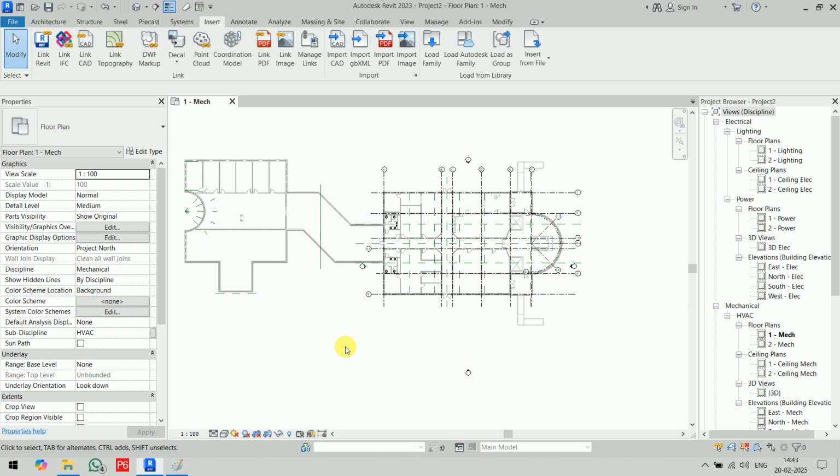As you learned in AutoCAD, we have an option called layers. In layers, if we lock the layers, that means they will freeze. We will not do any modification. In Revit, we have an option called pin. Pin means we will lock those things. We will not be able to change those locations. Any modification we cannot do until we unpin those projects or items, whatever is pinned.